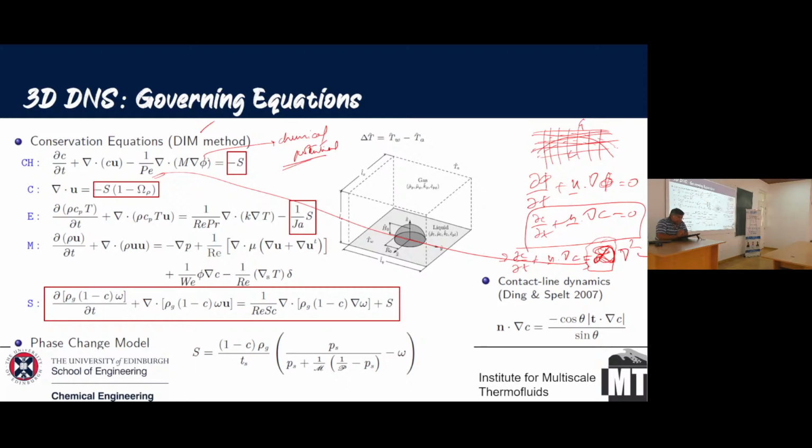There is a major advantage of this method: you can solve contact line problems without slip velocities. The other advantage is that because it's a diffused method, the interface will always have a certain thickness, typically 1.5 delta x, delta x being the size of the grid. If you have a thick interface, then whenever you have mass transfer, you can easily fit a mass transfer profile there.